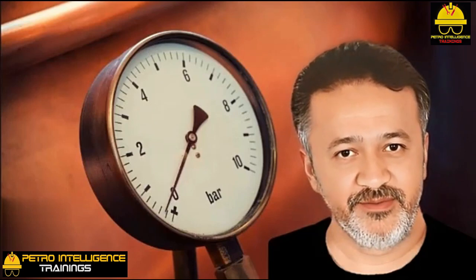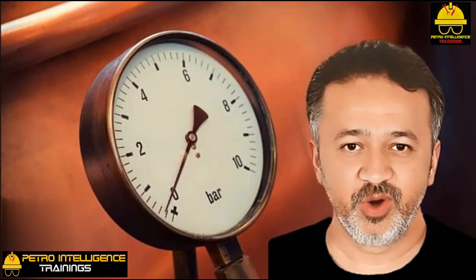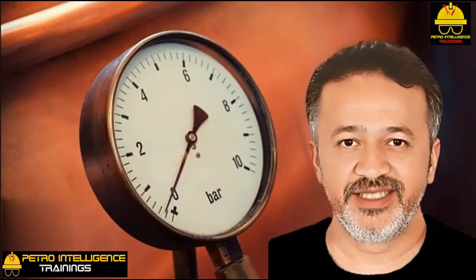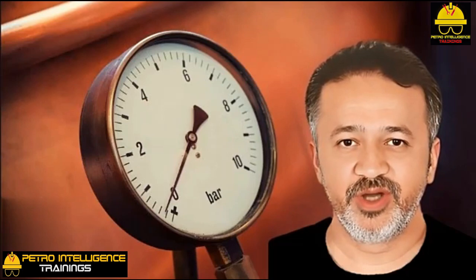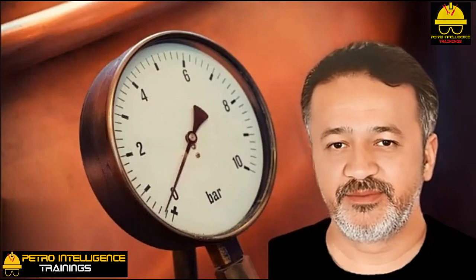To verify that fouling of a thermowell is a problem, place a piece of loose insulation over the exterior thermowell assembly. If the indicated temperature rises by 5 or 10 degrees Fahrenheit, then fouling on the outside of the thermowell is proved.